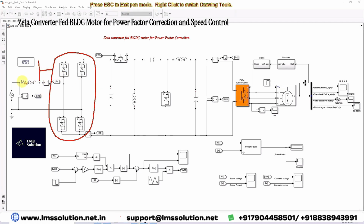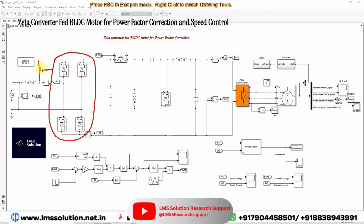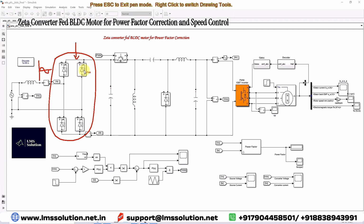Normally, when you directly use this AC supply to drive an AC load, the current will be sinusoidal. When we use this kind of load, it is considered a non-linear load. That means the diode rectifier is considered a non-linear load. So when you use this non-linear load, the nature of the source current is non-sinusoidal. You will get this kind of waveform in the current. We need to make the nature of this current sinusoidal. For that, we go for a power factor correction circuit.